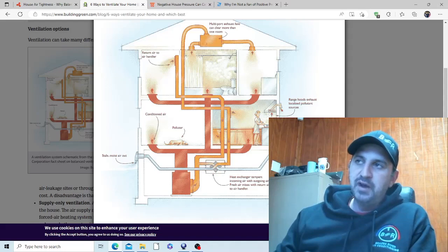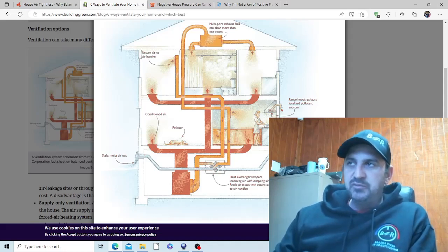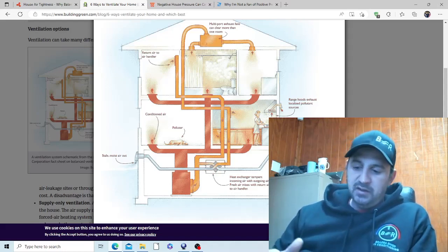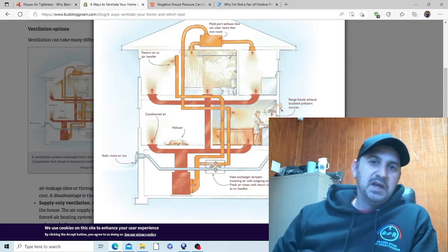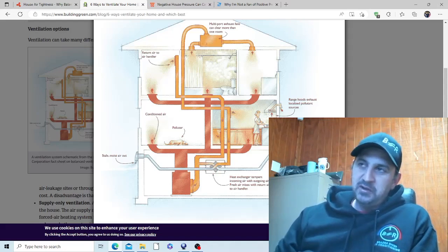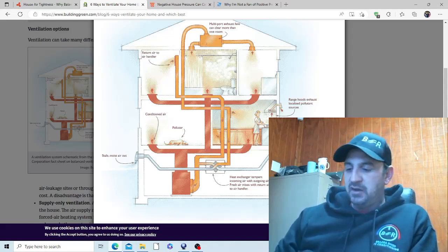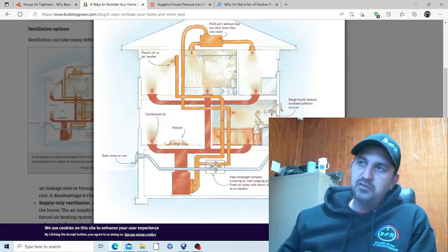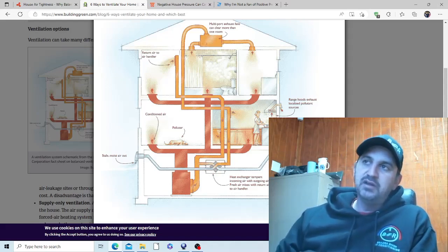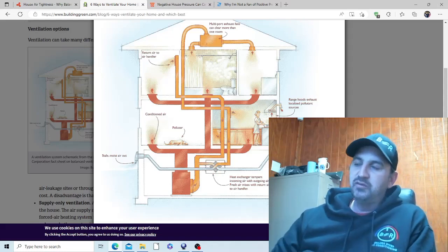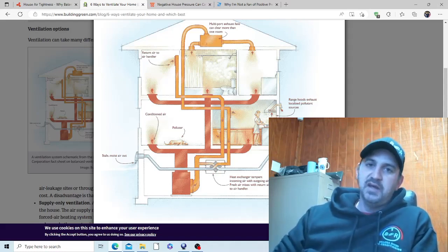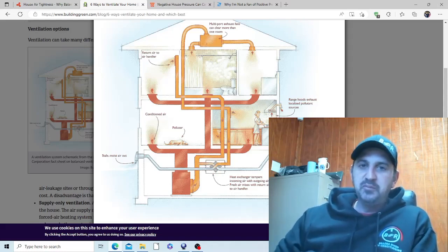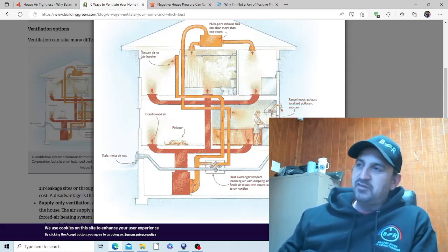Past that, there are other chemicals. Acetone is a big one that comes up a lot, because of paint, if you're painting a room or removing paint, painting your fingernails, or spraying your hair. All of these things will add acetone into a home. If your spray foam wasn't mixed properly and it's off-gassing, acetone will be released into your home. At that point, you need to address the spray foam as well. But just as an example, that'll be added into your home.